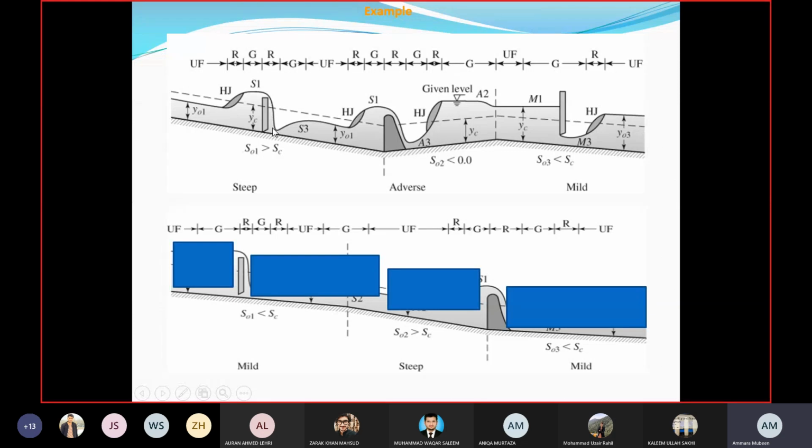here the water surface profile, you can see that it is crossing the control section. The water surface profile should cross the critical depth line. Now here you can see that for supercritical flow, like in zone 3, the value is less than YC in zone 3.